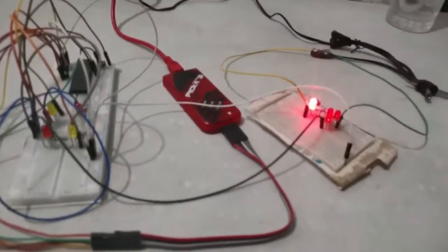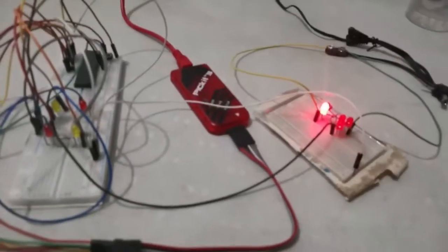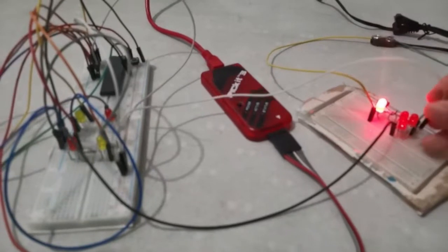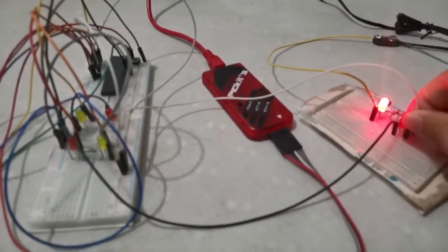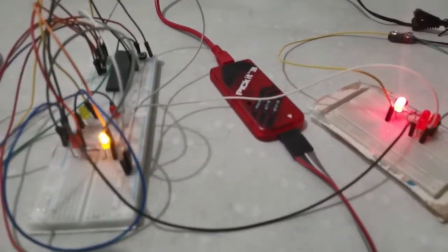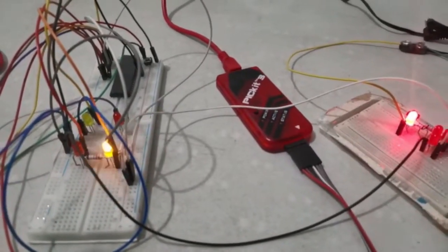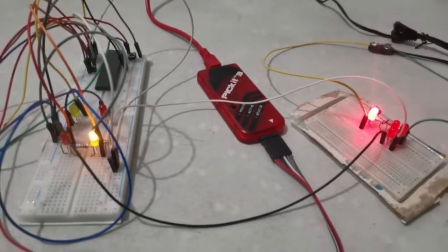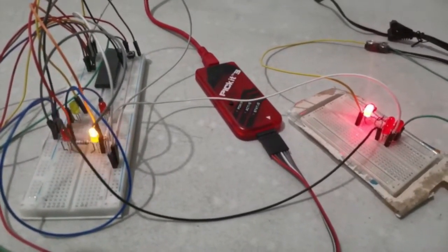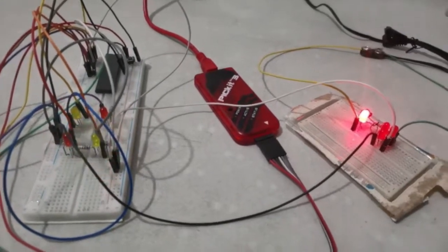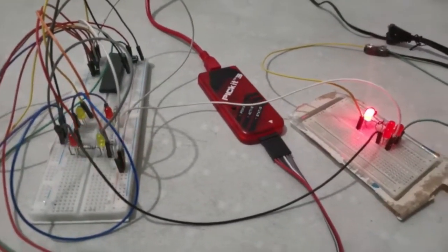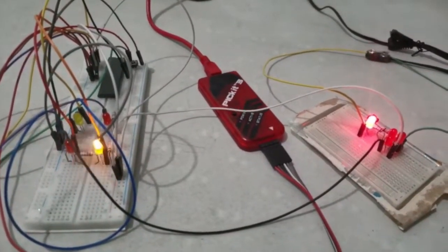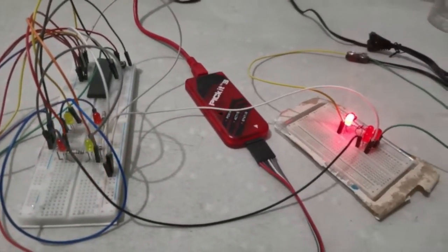So this approach is using our interrupt service. In here we'll have to activate this power supply, and you can see that the LED is blinking on and off with a period of about 250 milliseconds, where the timer has been designated to have a period of. So the extra challenge for the next part of the experiment would be to program the interrupt to be going on at an interval of 2 seconds.